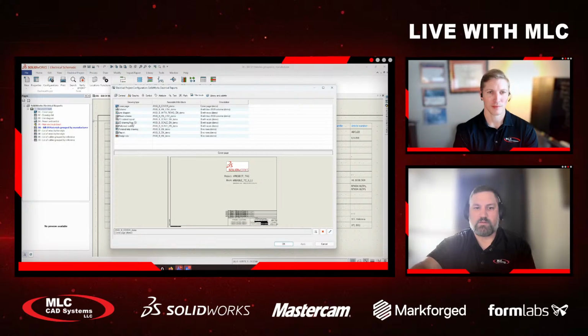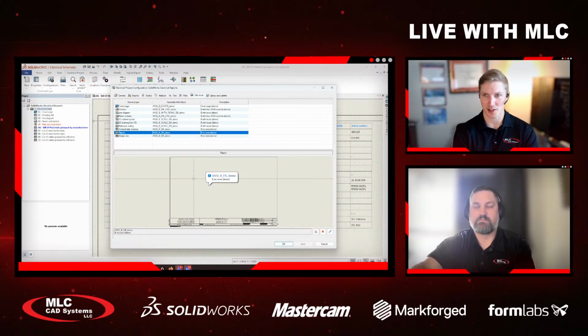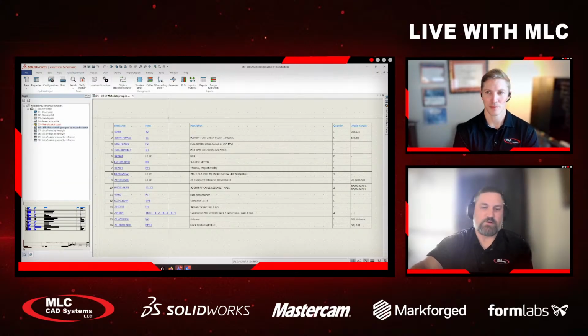One of them is a report, and that's the title block we're using here. If you wanted a totally different title block on this project, this is the place you'd change that, for every report. If you wanted just this report, you would right click on this and go to title block, and then you would replace it. So it's a sweeping change versus just this one, a subtle difference.